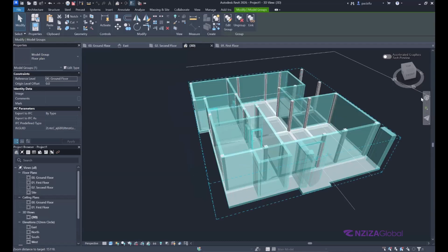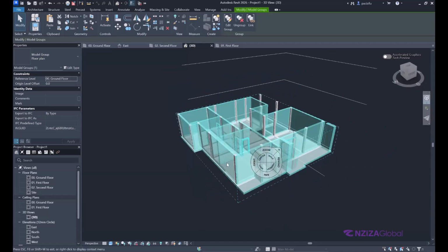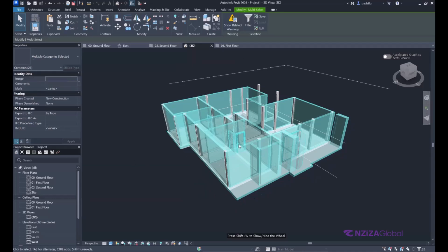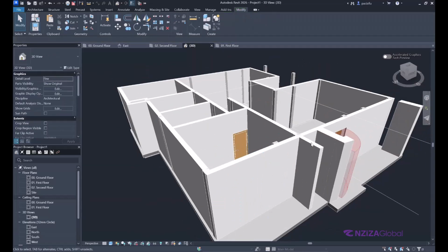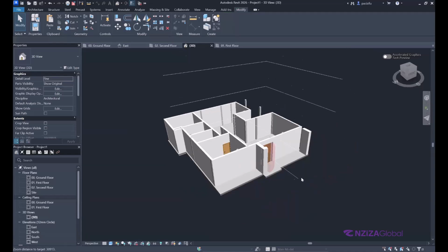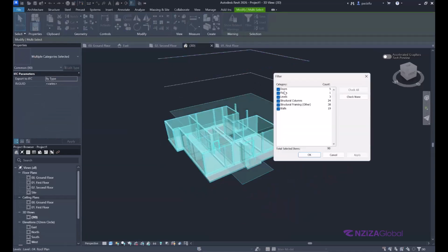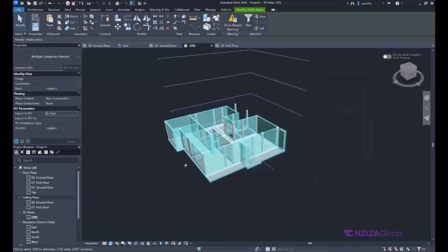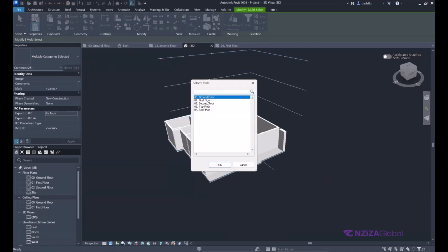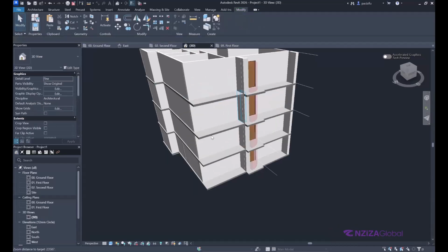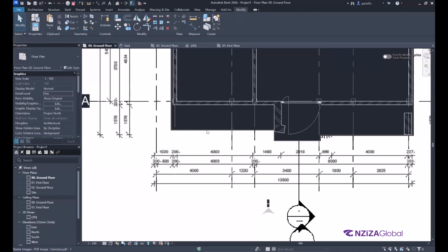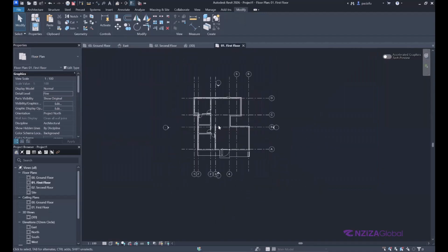So now we are not doing apartments which are the same. I don't need this group. Let me select it. Levels. I deactivate even those columns. Yes. Now I can do the copy, paste, align to levels, this and this, then okay. So I'm going to use this to edit each floor. So for the first floor,